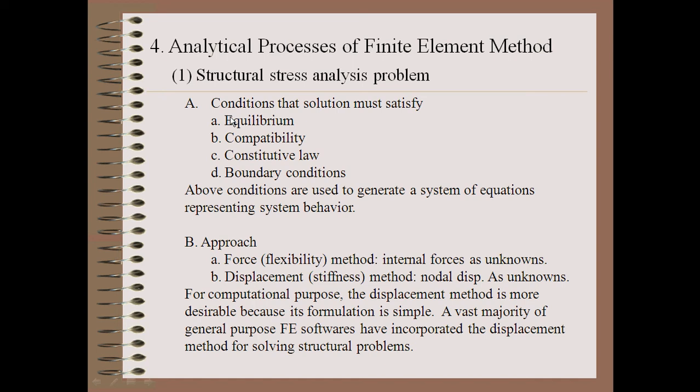And if you look at the analytical process of finite element methods, and if you take a structural stress analysis problem, first are the conditions that must be satisfied by the problem. That is equilibrium, the system is to be in equilibrium while solving the problem, and then compatibility, and then the constitutive law which governs the behavior of the various parameters in that particular system, and the boundary conditions, of course.